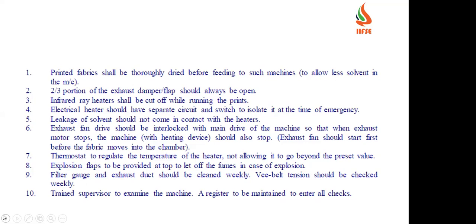Then the exhaust fan drive should be interlocked with the main drive of the machine, so that when the exhaust motor stops, the machine with the heating device should also stop. It is about the exhaust fan. So whenever the exhaust fan stops, what will happen? The machine also should stop. Whenever the exhaust machine is not in working condition, if the machine keeps on running, what will happen? The fumes get accumulated in the whole working area.